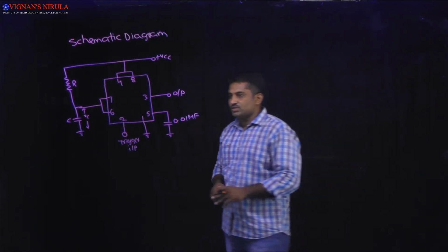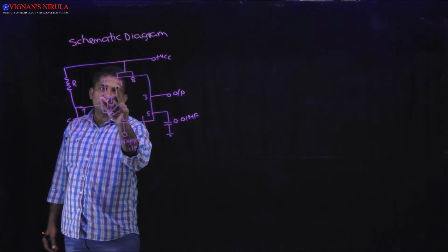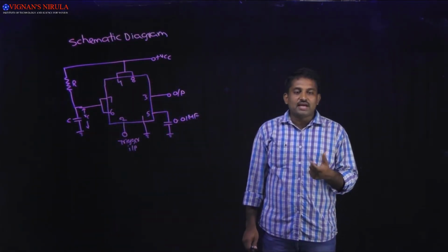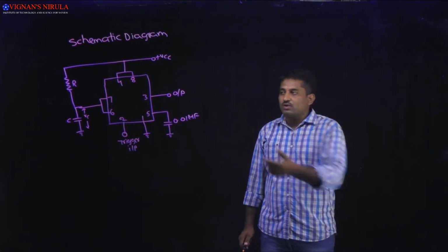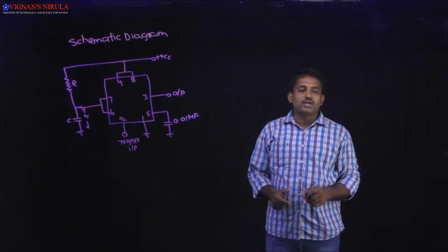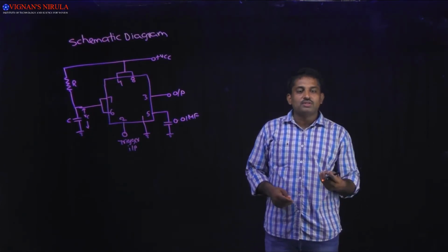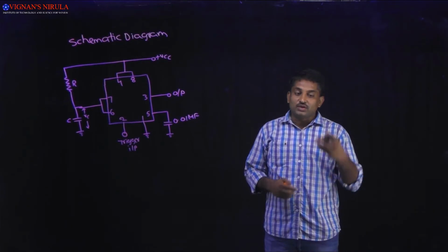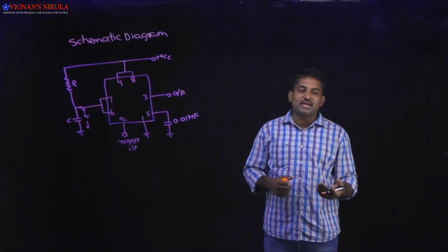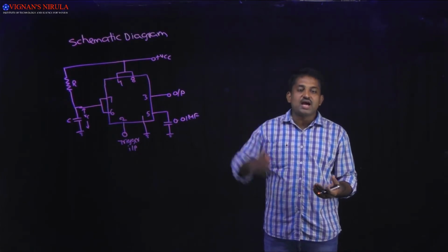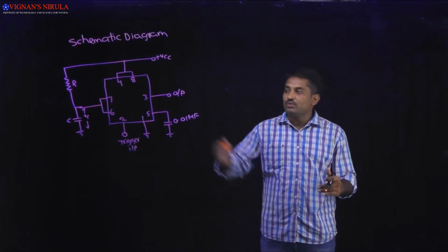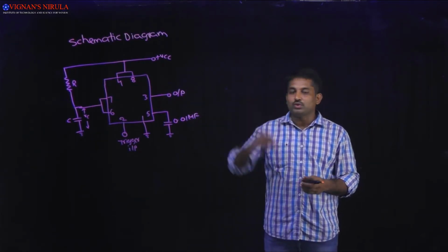Now coming to this one, here pin number 4 is connected to VCC. Why? Because to avoid accidental resets, we connect pin number 4 to VCC. Generally, if you connect pin number 4 to ground, then what happens? It overrides the functions of IC555. It acts as an on and off control switch for the IC555. So, to avoid the accidental reset, we connect the fourth pin to VCC.